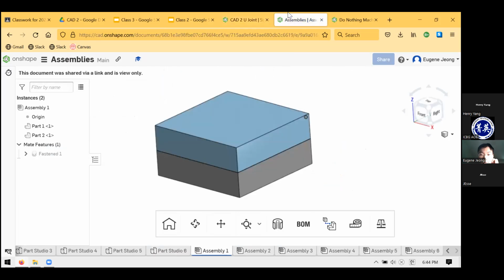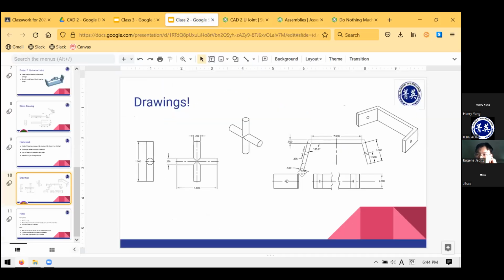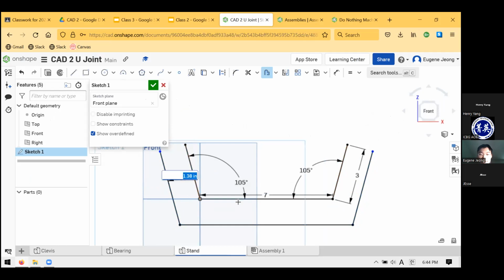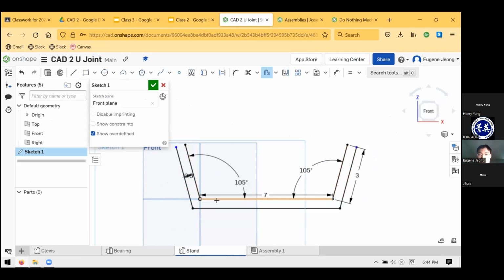Looking back at the drawing, I can see that what I drew was basically these 3 lines here, the inside of the base. What I want to create are another set of 3 lines that are the outside, these 3 lines. And I know that they're separated by a normal distance of 0.5 inches. So I'll just drag this arrow back. It's kind of like a sketch pattern in terms of how you interact with it. For the number, I'll just type in 0.5.